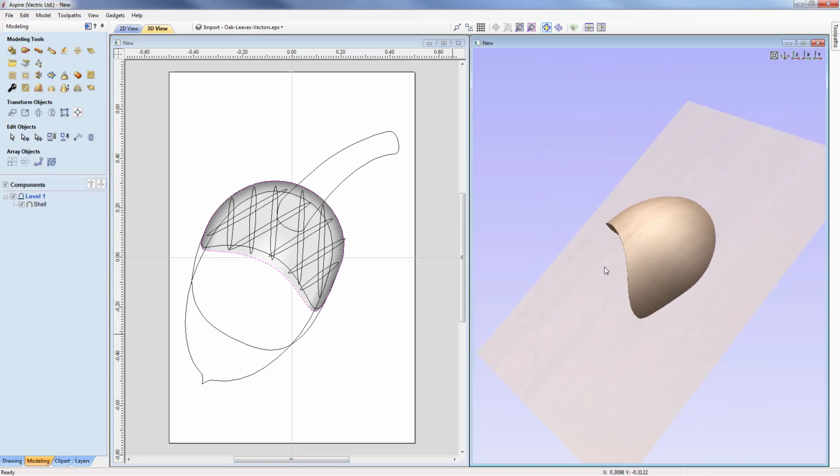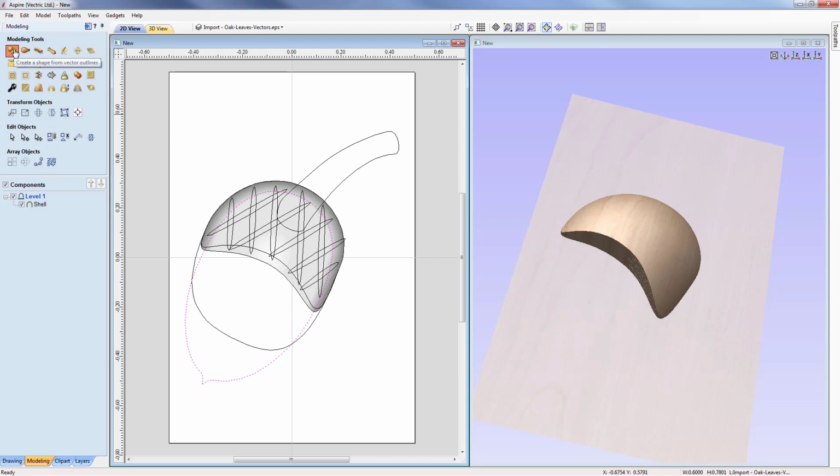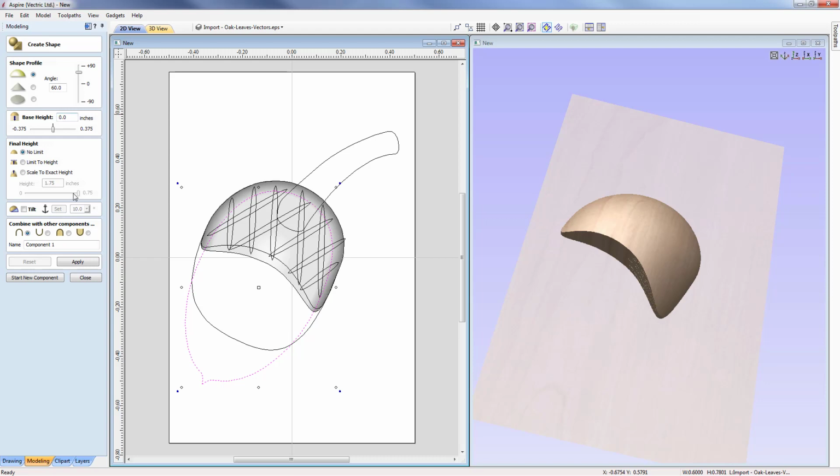And now we can think about adding the main acorn into that. So that's what I'll do next. I'll pick the main shape we've got here and come back into the shape editor. Okay, and we'll look to, in this case, not add it to this particular shape, but actually to merge it into it. So we're going to select the merge option here.